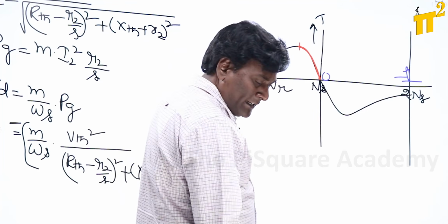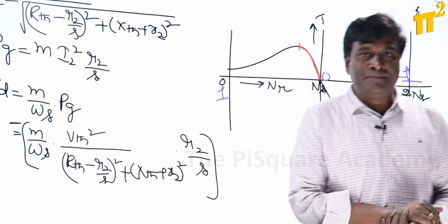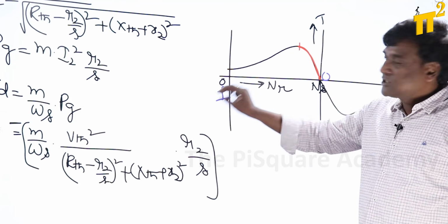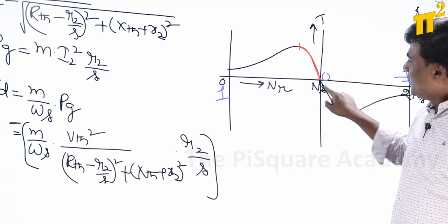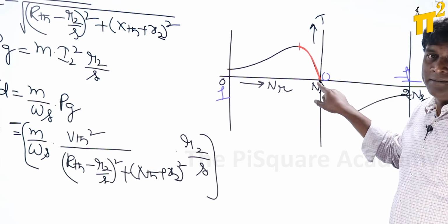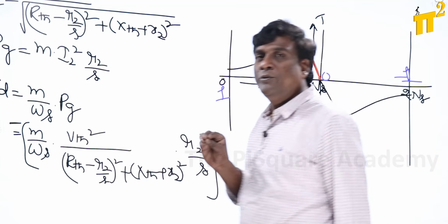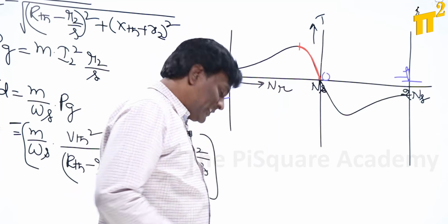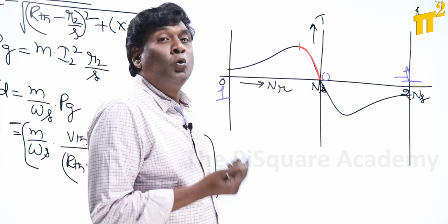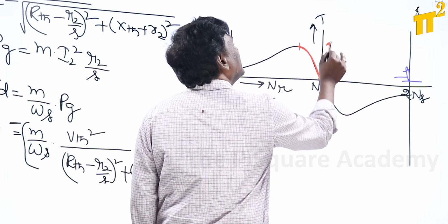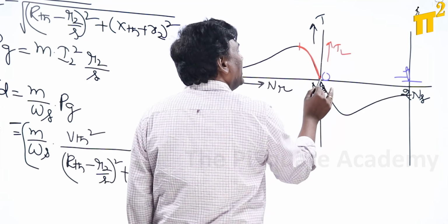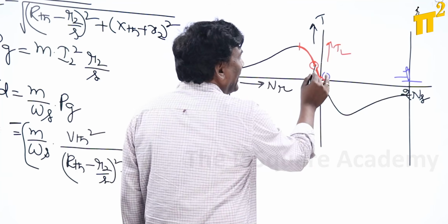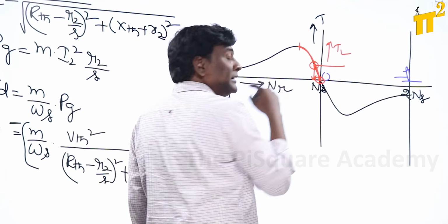For example, an induction motor is working under no load condition, meaning that load is not there. You switch on the induction motor, some torque is there, and it will start rotating almost at the synchronous speed. An induction motor at no load will start rotating at the synchronous speed. After that, if you keep on increasing the load, the torque will be increased, and in order to meet this torque at this speed, it is going to rotate.